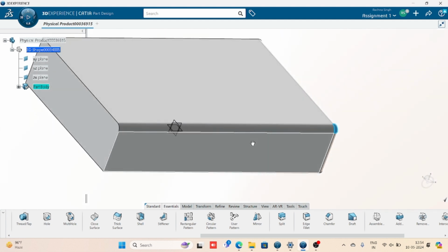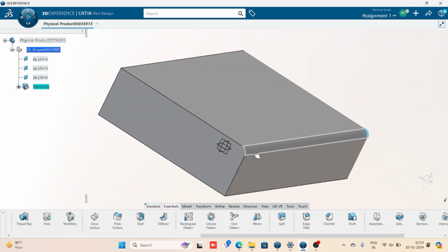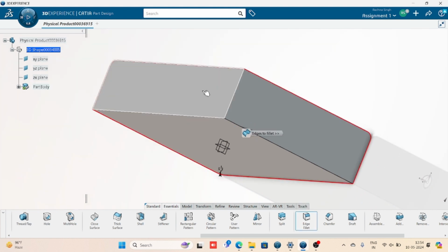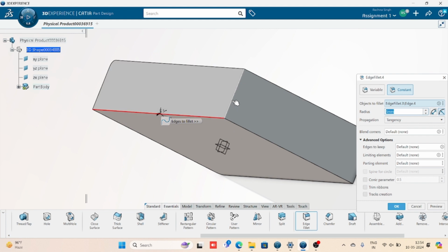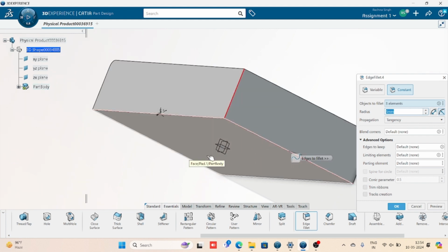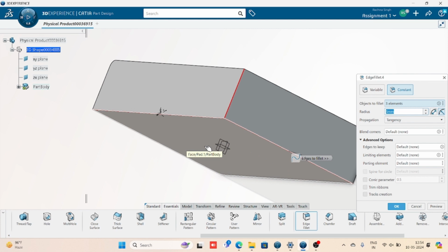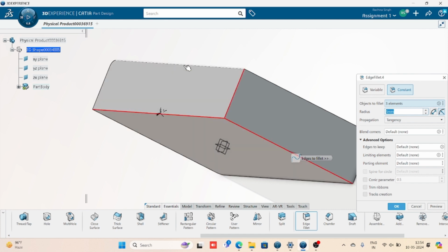Now I want a corner which is defined very first, and then the governing edges should be filleted. So in that case, we'll select all the three edges. We can do the fillet in one command, all the edges all together, but that's supposed to be one fillet radius. If the fillet radius is different, then you have to go again and again. But if the fillet radius is one, then you can go for one command only, and you can select all the edges which are of the same radius all together.